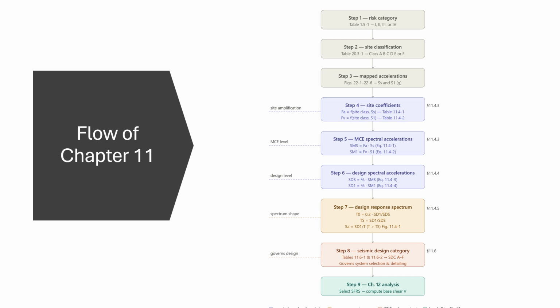So you're going to have a very low vibration period because you don't have a lot of ductility within that structure. A steel frame is a lot more ductile than a concrete frame. So you're going to have a difference in the period at which you're going to design that structure for.